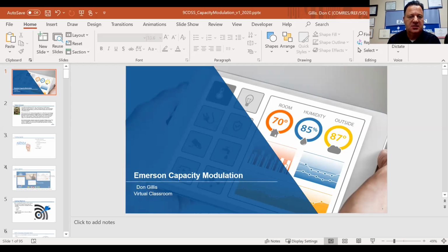Talk a little bit about the mechanics, compression, and radial compliance. The radial compliance is going to be side to side, and I'll touch a little bit on that to show you how that works. Pressure balancing, and more importantly, the axial compliance is what I really want to show you, especially when we get into digital, because I want to show you how that works, not just with the fixed scroll, but how it comes into play on our modulation compressors also. And then we've got high side pressure, everything above that blue plate, that muffler plate, and then internal pressure relief and TOD and lubrication.